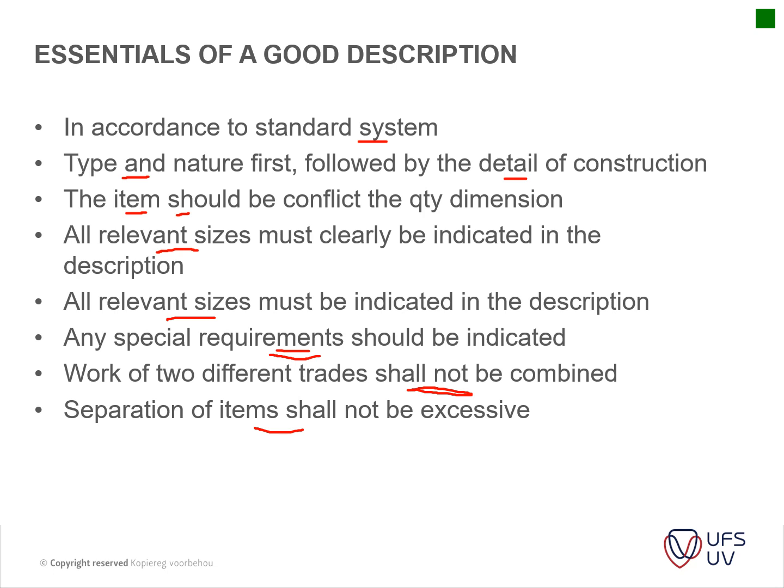Okay, so you're not going to describe the construction of a steel gate now with each little steel section measured out in length together or into different sections. That's just going to be too excessive, and the contractor won't be able to actually understand what needs to happen. So if ever you have a special ad hoc manufactured gate, you will have the description usually linked with your drawing or so. You give the size, you might even give the weight of it, and then the contractor should price that as a unit.